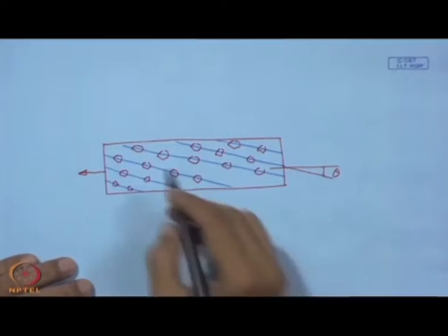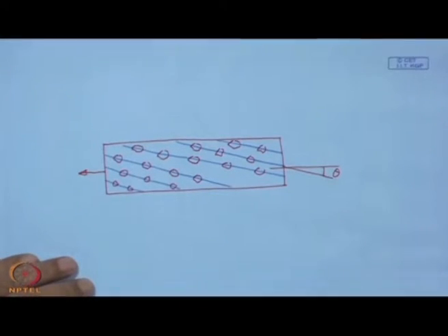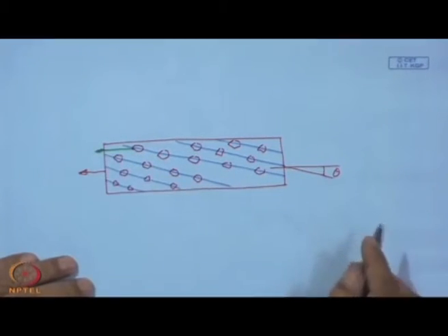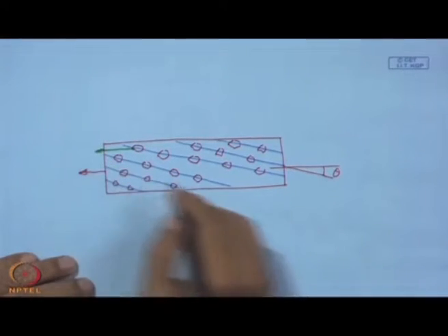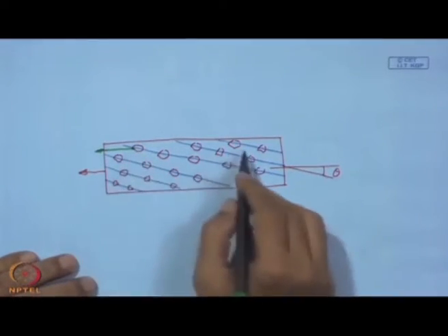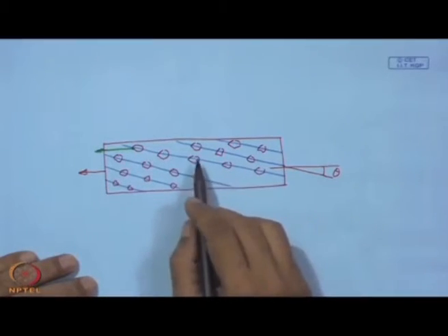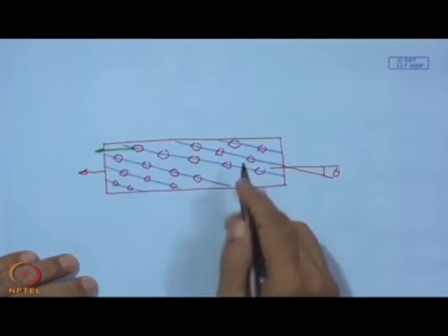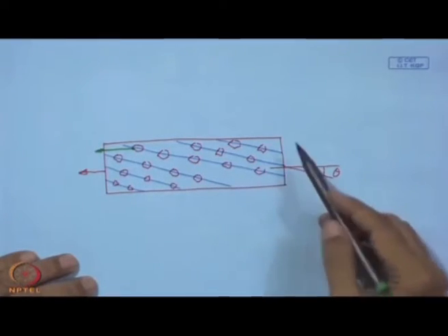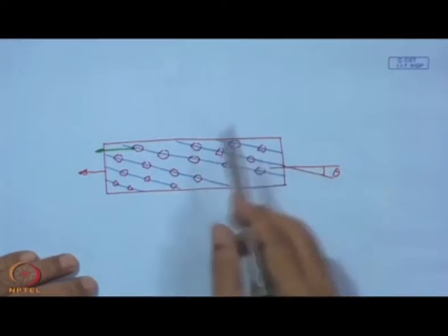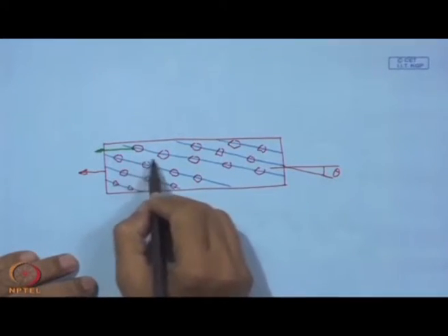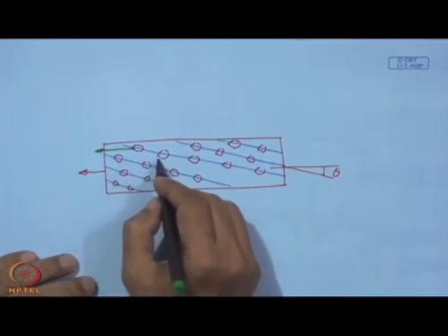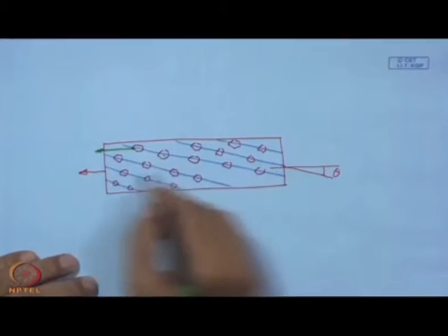Here we can see that each grit has its cutting action in this direction, but in the direction of motion we get more number of lines. That means, just by having this angle of obliquity, we have so many grits not just along the helix line, but a little oblique to it, and that is why we have more scratch marks for each cutting point.